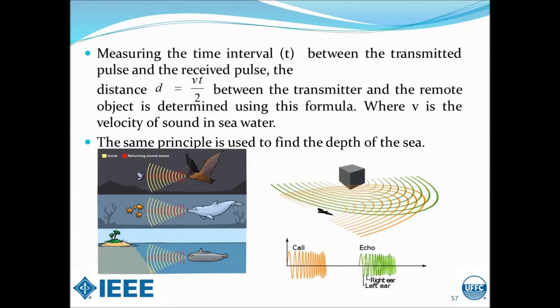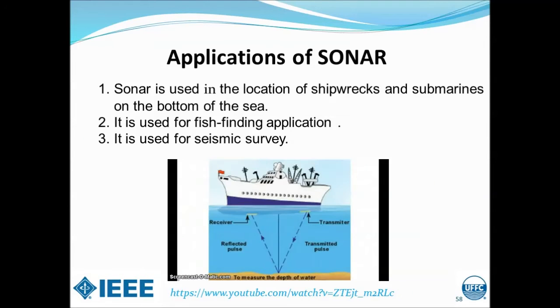By measuring the time interval between the transmitted pulse and the received pulse, the distance d equal to vt over 2 between the transmitter and the remote object is determined using this formula, where v is the velocity of sound in seawater. Sonar has a wide range of applications, including locating shipwrecks, submarines, fish finding, and doing seismic surveys.